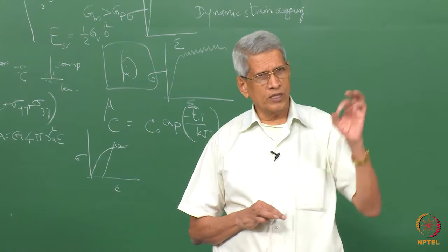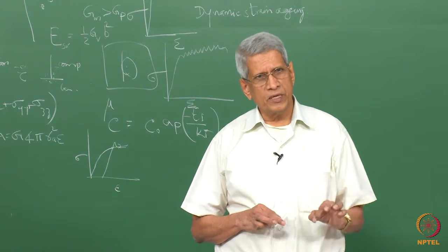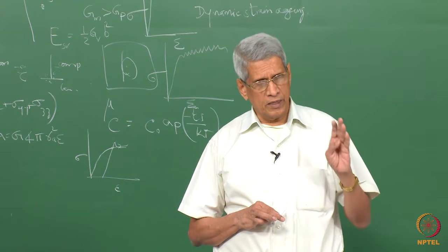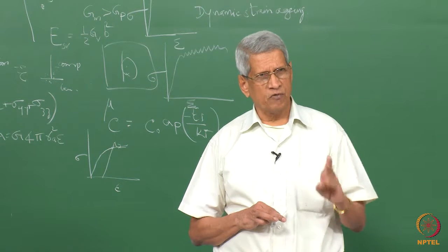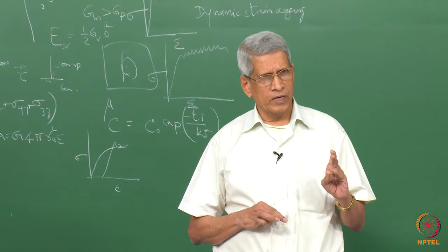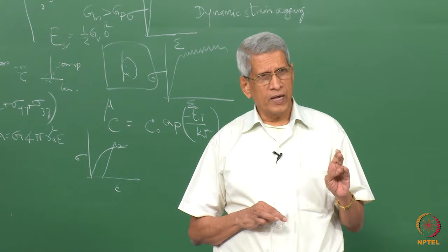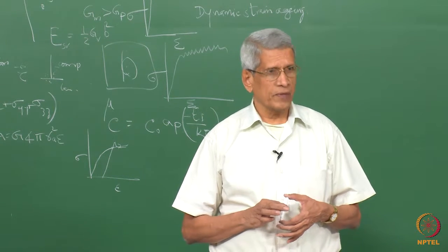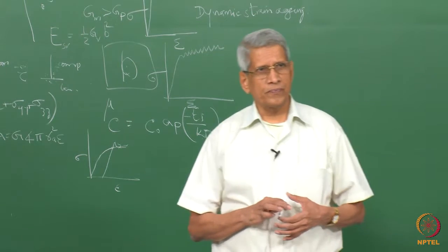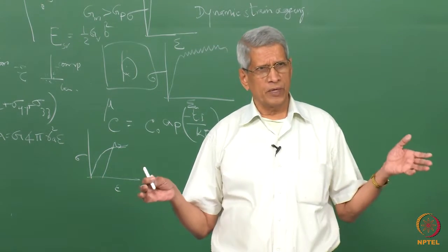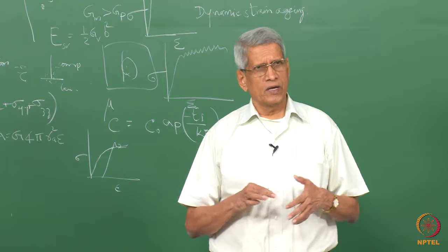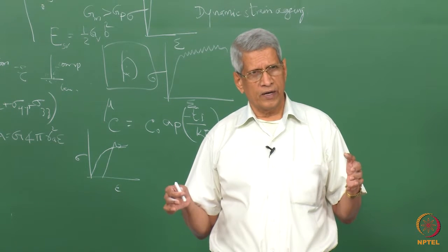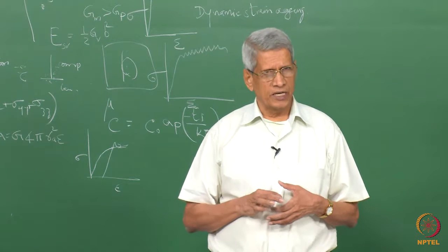So far in this course, I initially mentioned the three types of volume defects: stacking fault tetrahedra, precipitation, and voids. Voids can form during irradiation. Stacking fault tetrahedra can also form in some materials, because of materials with low stacking fault energy, and because of some specific type of dislocation interaction.